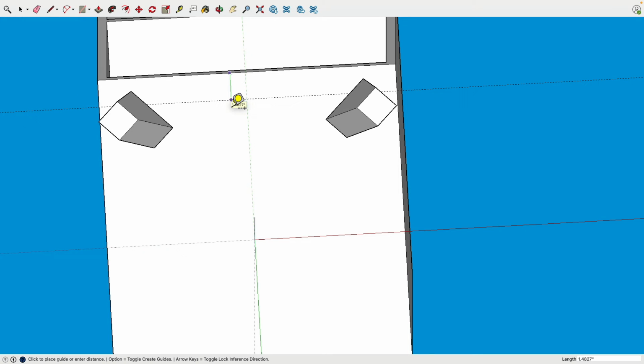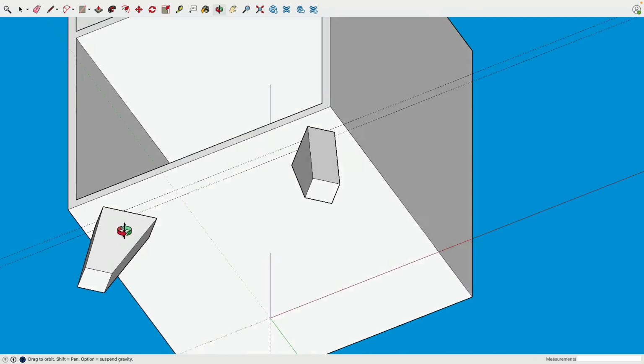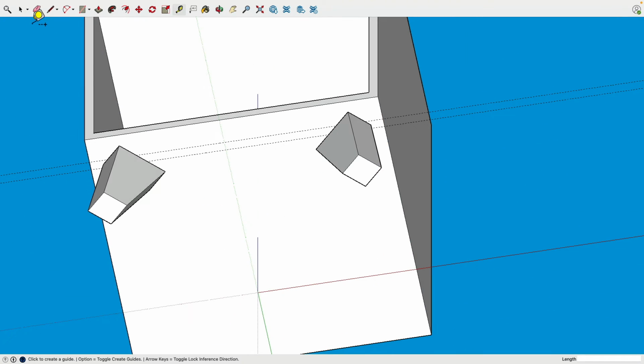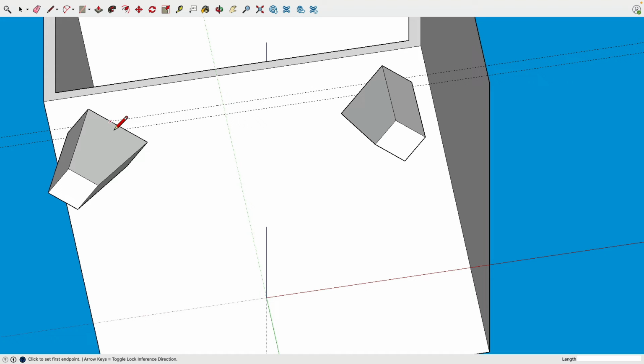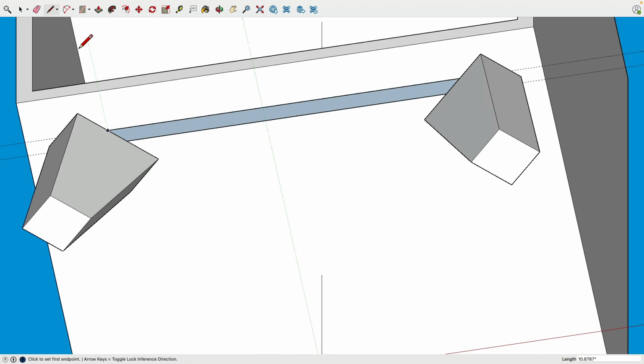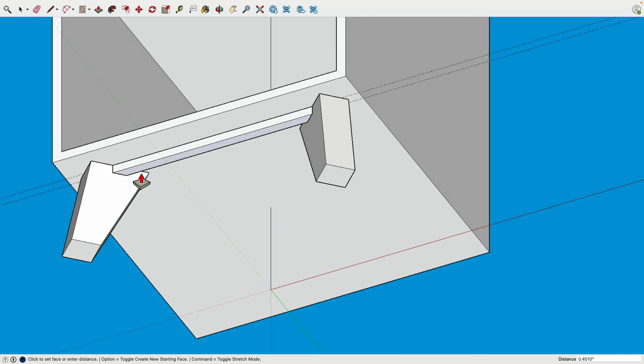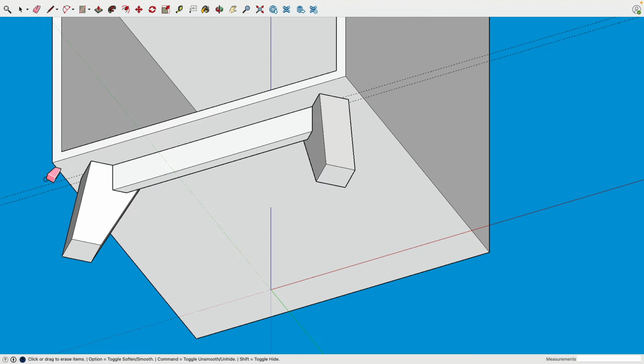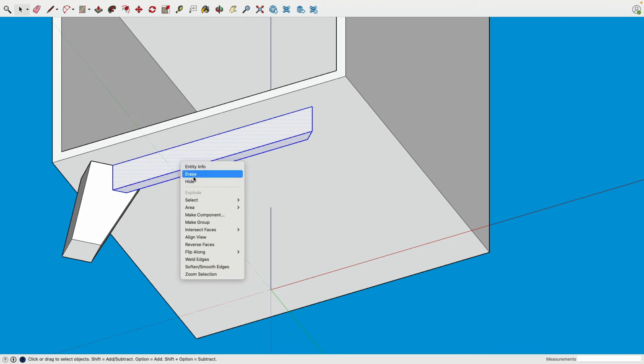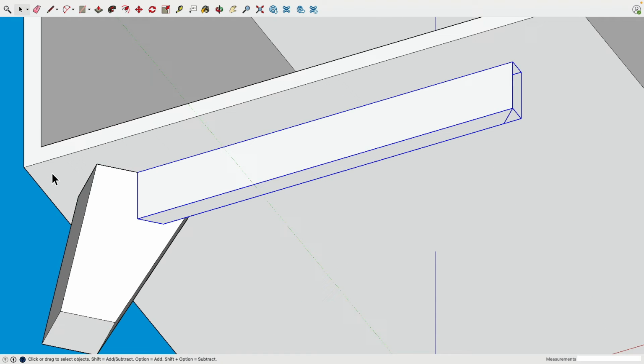An inch, 1.5 inches. Okay, and another 0.5 inches. This looks good. And then where everything intersects, we simply draw a new set of lines. And extrude this one down by 1.5 inches. Cool. This can go, by the way, triple select, right click, say make group. Very good.